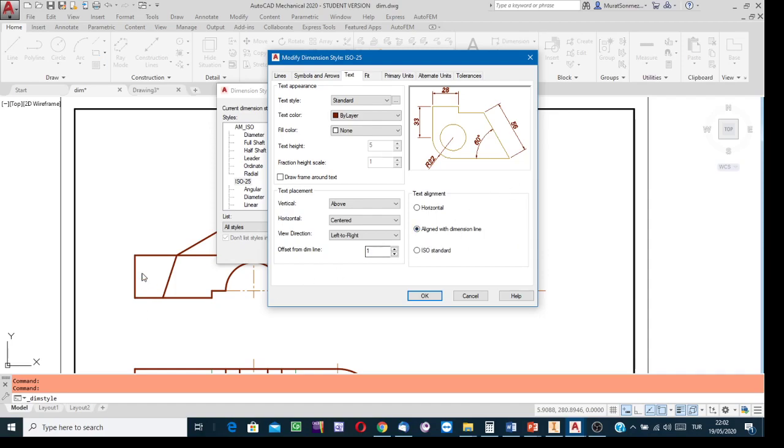So if it were third angle projection, I would say to select the horizontal option. It is to have the dimensions not in alignment but always horizontally oriented. But this is first quadrant projection. ISO is the standardization organization to obey, and it says to show the dimensions in alignment with the dimension line. So this radio button is correct. In this dialog, these are the things to do.